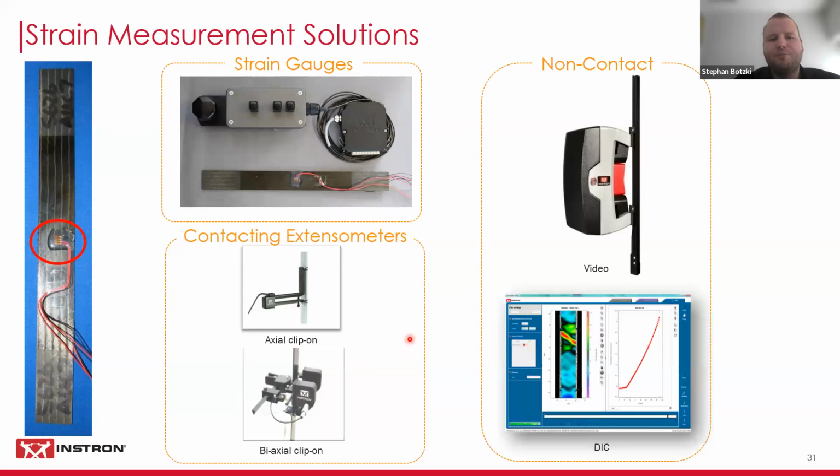But really, if we look at those videos earlier, extensometers are going to have a rough day, right? If we have those explosive failures, they're eventually going to be damaged or even completely broken if you test over and over, and they just get impacted by all those high energy releases. So video is really the way to go, as long as the video extensometer meets the accuracy requirements of the standard. And the other advantage, obviously, is that your operators don't need to attach anything manually. That is obviously a great advantage.